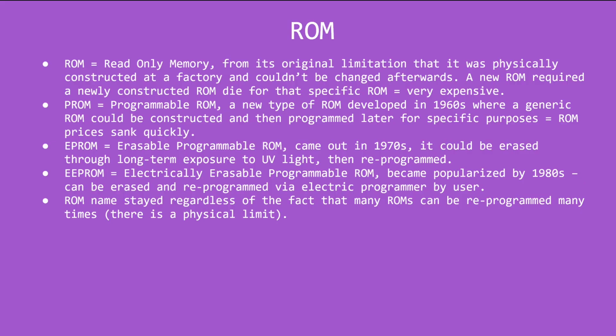As I said, the ROM name just kind of stayed regardless of the fact that technically after a certain point they weren't ROMs. And you'll see them in all sorts of uses, and you can get EEPROM modules to use with your microcontroller. Keep in mind they're a type of flash memory, or flash memory is a type of them. So yeah, it's not meant to be constantly used like a hard drive, but for access amounts these days, you're probably fine. And they're so cheap that if one goes out on you, you can probably replace it for pennies on the dollar.